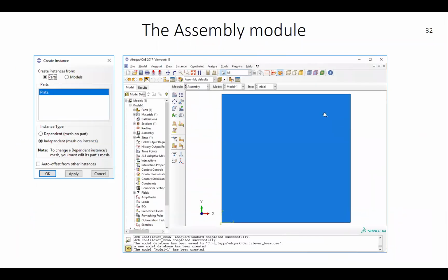We go to the assembly module, just insert our only part, which being this slab. You may, if you want, assemble 3 slabs which correspond to problem A, B, and C, I think they're called in exercise A. But it's better to do them separately, because if you include them all and do the analysis of all of it, your system of equations will be much bigger.